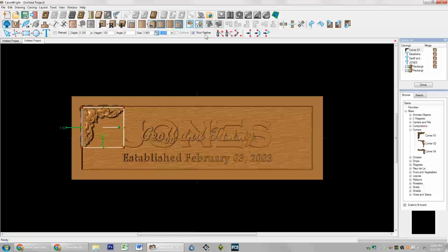Now on the height, we have a total of 6 inches, and I don't want it to overlap or even touch. So I'm going to go 2 7/8, which is 2.875 inches. And then on the width, just because I did this a couple times before, I know that I'm liking the way it looks at 5 1/4 wide. That's something you could totally just play with and get whatever you want.